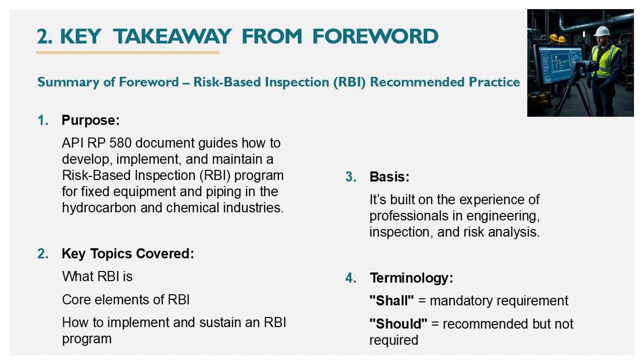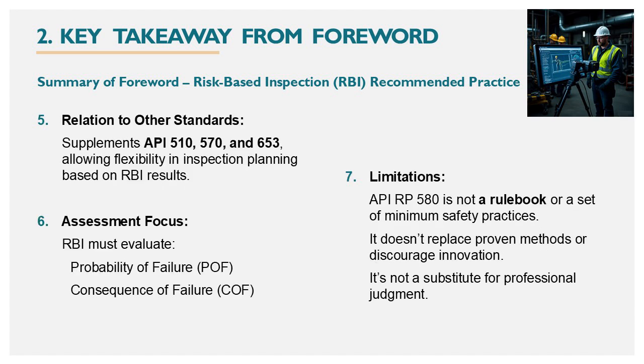It's built on the experience of professionals in engineering, inspection, and risk analysis. Number 4 is terminology. Shall stands for mandatory requirement, and should stands for recommended but not required. Number 5 is relation to other standards. API 580 risk-based inspection recommended practice is a supplement to API 510, 570, and 653, allowing flexibility in inspection planning based on RBI results.